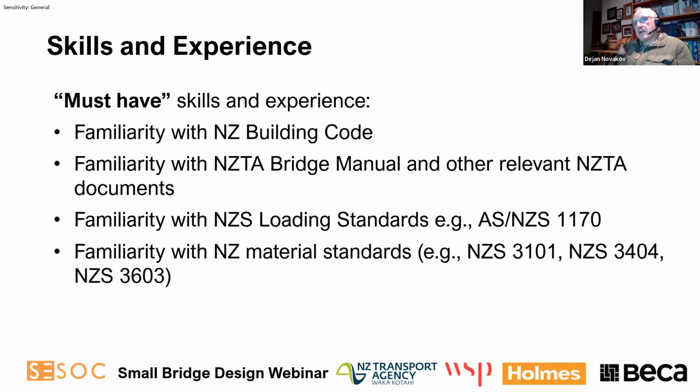Also other NZTA documents like highway structures, probably, if you're not using the bridge manual. You must be familiar with the New Zealand loading standards, for example AS/NZS 1170 parts, and as Matthew said, also with New Zealand material standards, timber, steel, or concrete.